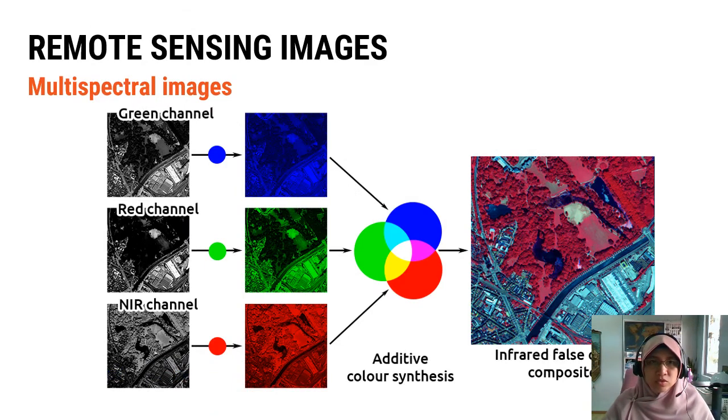Multispectral data are acquired by simultaneously recording 3 to 8 different spectral bands that may or may not be contiguous. To visualize this information as a color image, the primary colors red, green, and blue are paired with spectral bands. The relative brightness, which depends on the digital value of each pixel in each primary color band, determines the resulting color in the combined band.